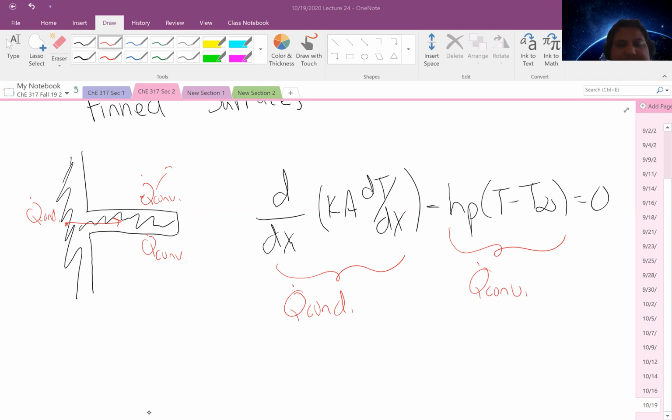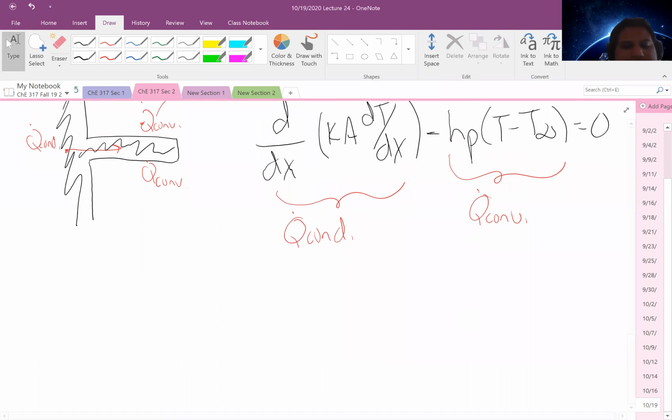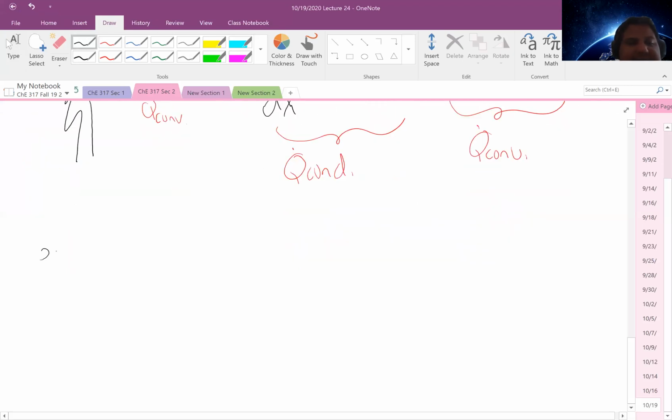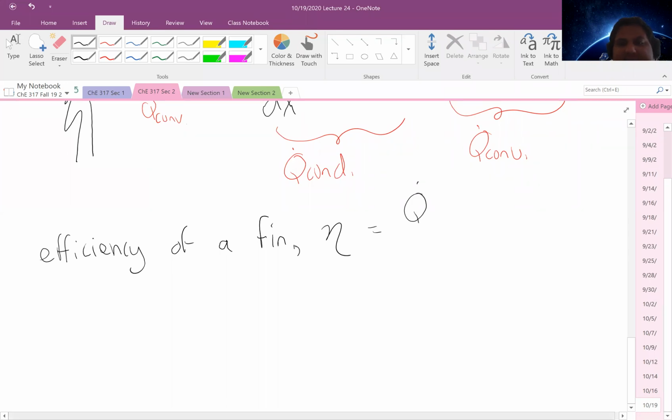We're not going to get into it primarily because it's a little lengthy in the discussion, but it's important to consider both the fin efficiency and the fin length of a system, where you can consider the efficiency of a fin, eta, as the heat conduction that exists in the fin over the maximum heat transfer that exists within the fin.